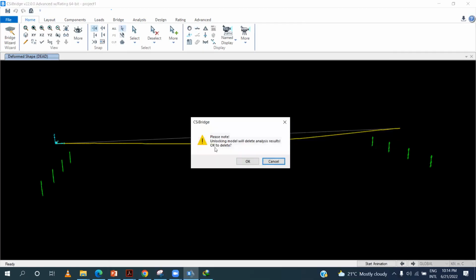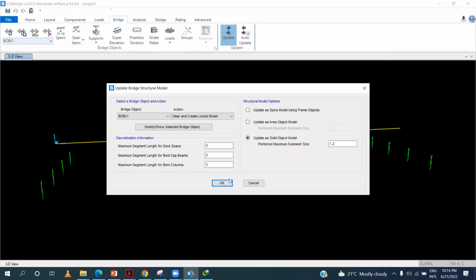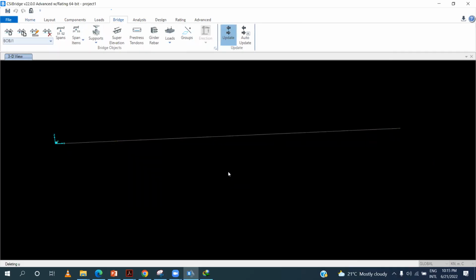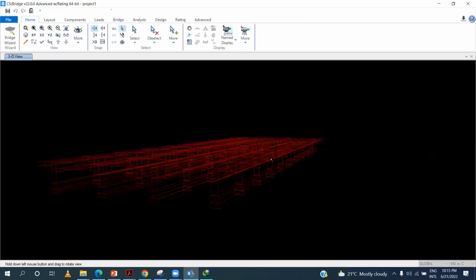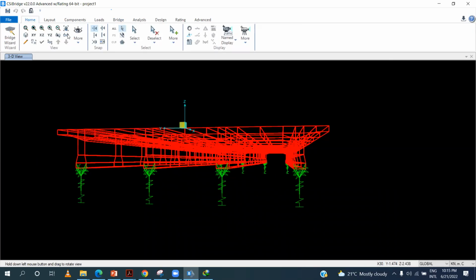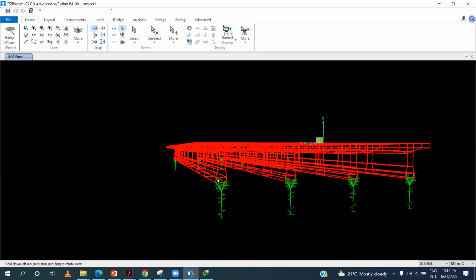And the solid model we do not use frequently for bridge design in practice, because the solid model is finite element modeling. It takes a huge amount of time for the system to analyze such models. Let me show you how the solid model looks. So this is a solid model. A solid is basically a 3D model. It is just like if you perform analysis in Abaqus or ANSYS, if some of you have used Abaqus or ANSYS, it divides it into a 3D object, and it will take a lot of time only to perform a simple dead load analysis.